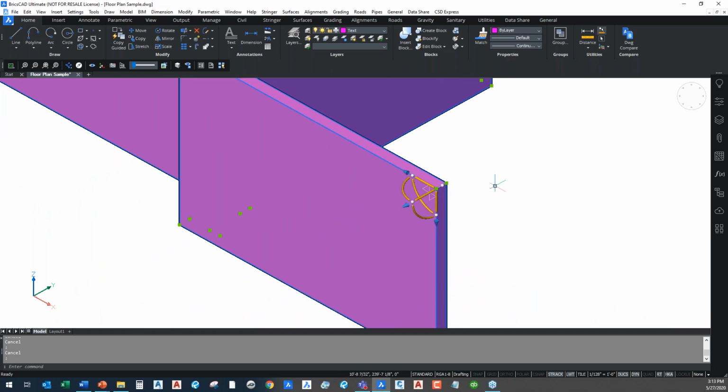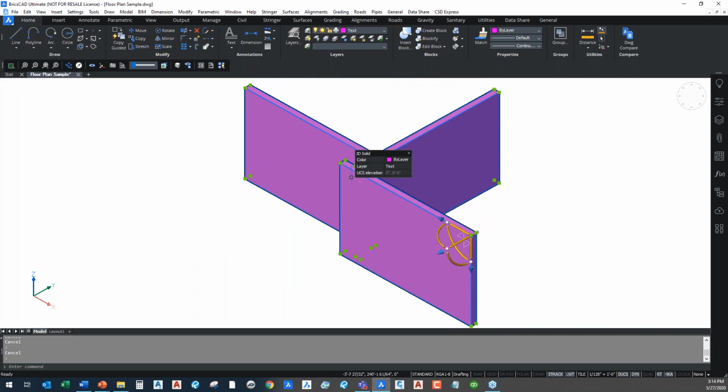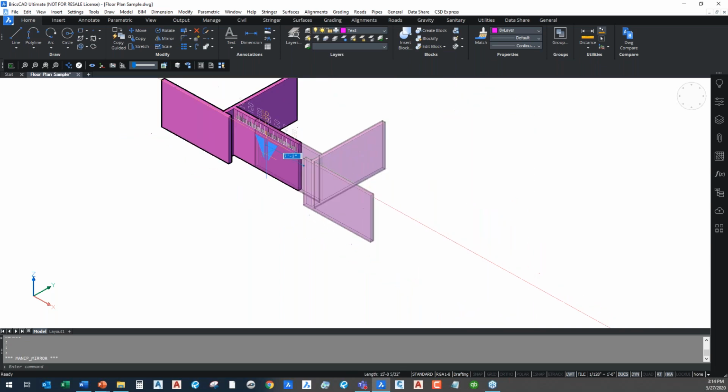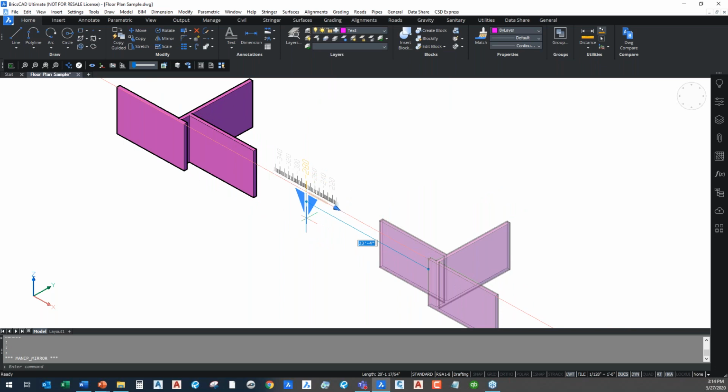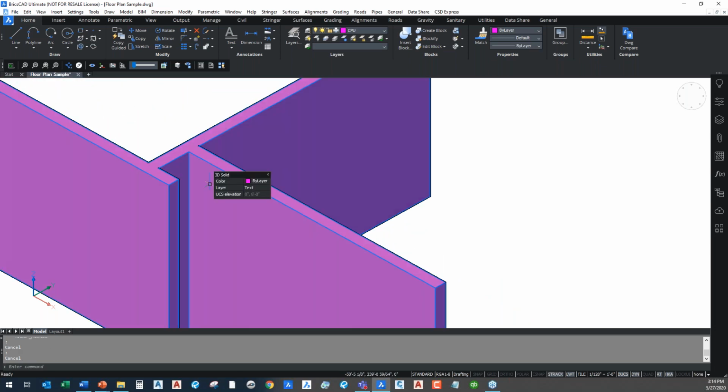I can even use the mirror commands. So again, like I said before, notice where the inset is on the right side, up in there. This little inset here. Just want to show you so you understand when we're mirroring things. So if I go here, I want to mirror over this plane. When I mirror, as I'm moving up here, you can see that that little inset is now on the left. It's not a copy. I just want to make sure you can visualize, I'm actually mirroring this a set distance. So if I need to mirror that 24 feet away, now it's flipped my walls.